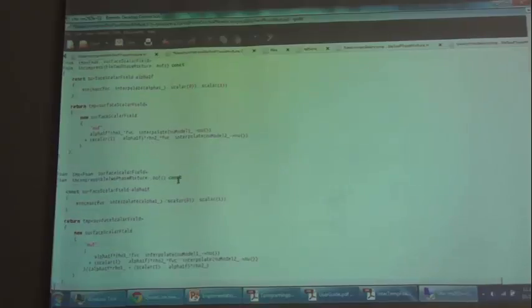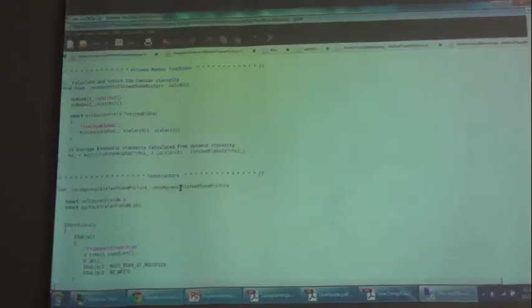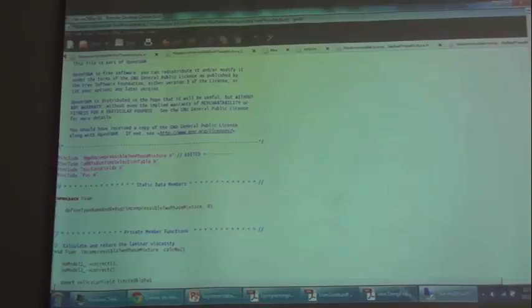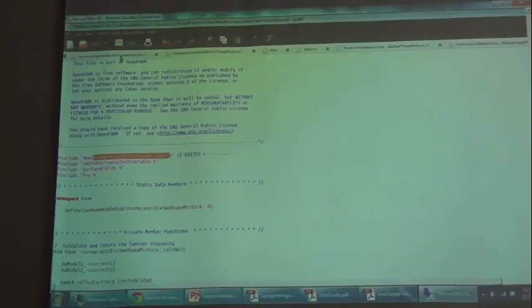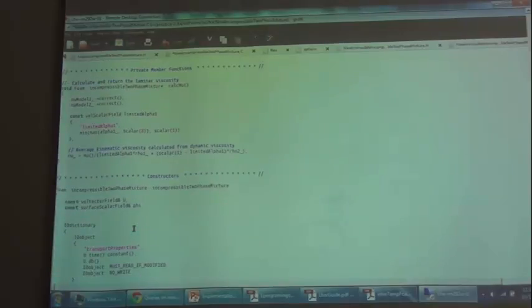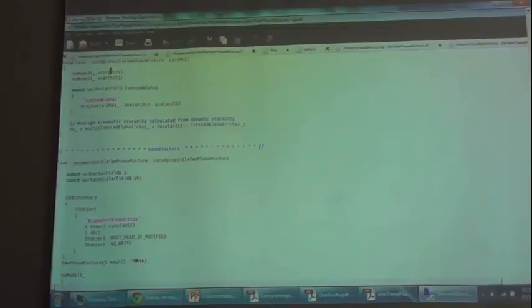Coming to the .C file, the first thing that you may have to modify is that initially, for the original interFOAM solver, this would be incompressibleTwoPhaseMixture.H. Now that you have modified and renamed the .H file, you have to make sure that you are accessing the newly modified .H file. So you rename this, and then you add the private members according to the definitions that have already been given in the .H file.